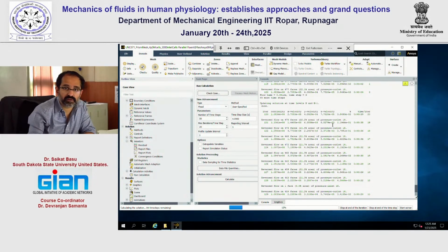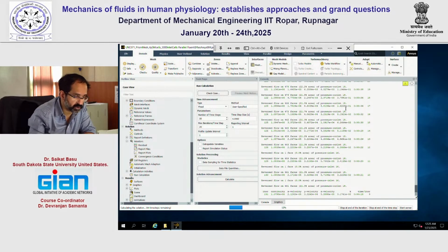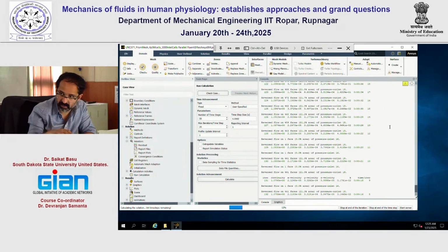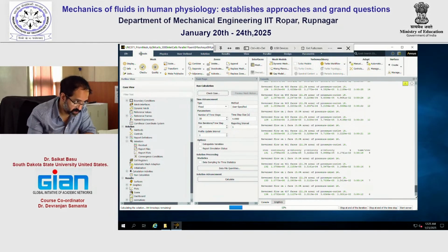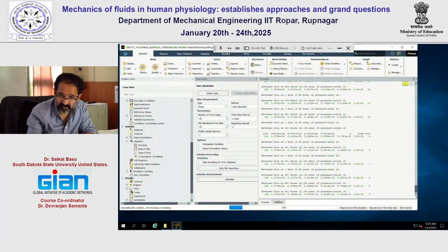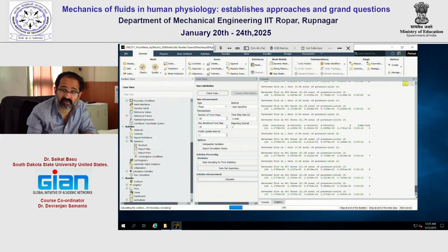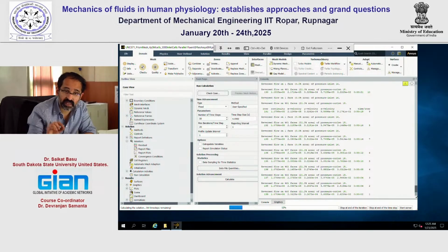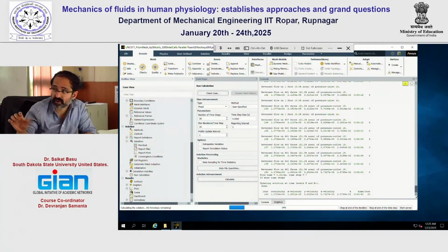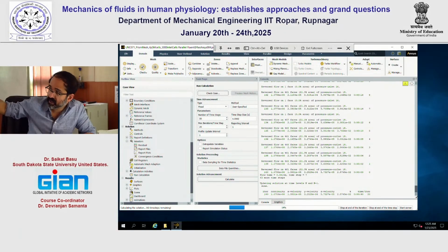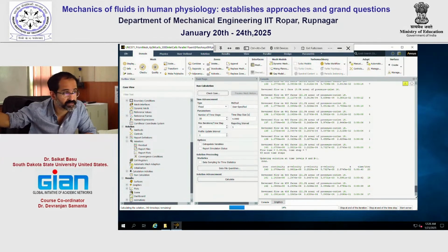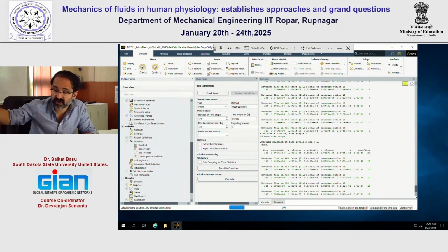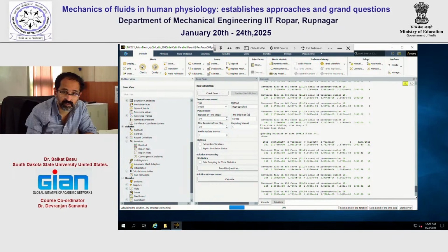But the thing is, you now have a good sense of how the simulation has to be started, right? And you can follow the protocol to do that. So you get the mesh file imported into Fluent and start the simulation. Once the simulation is done, this is important especially for folks who have not used ANSYS Fluent before, go to File and then Save Case and Data Files. The case file is the one that includes the mesh information and the numerical setup that we have built up. The data file is the data that is going to be generated. So you have to save both case and data files, and that is available from the File menu.